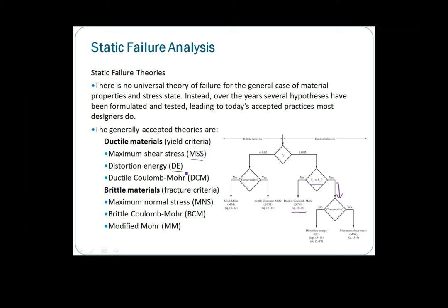If you are talking about a particular structure that is already there and we want to analyze it, we will want to evaluate failures closer to actual conditions. So for analysis, you have to use a less conservative theory, which is the DE theory. Later on we'll look into this, right?